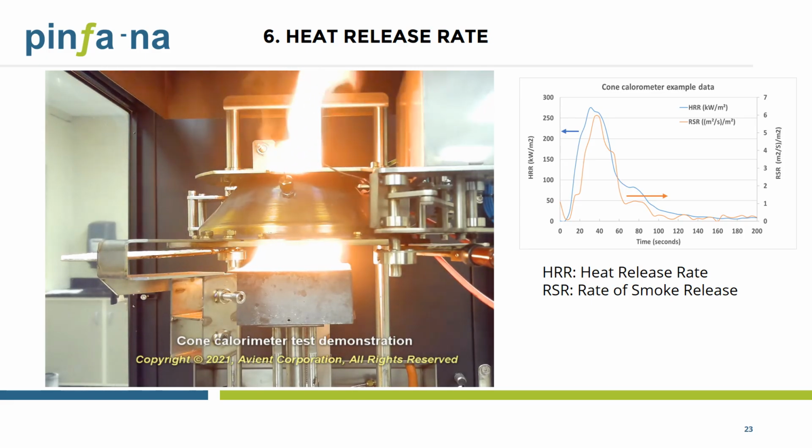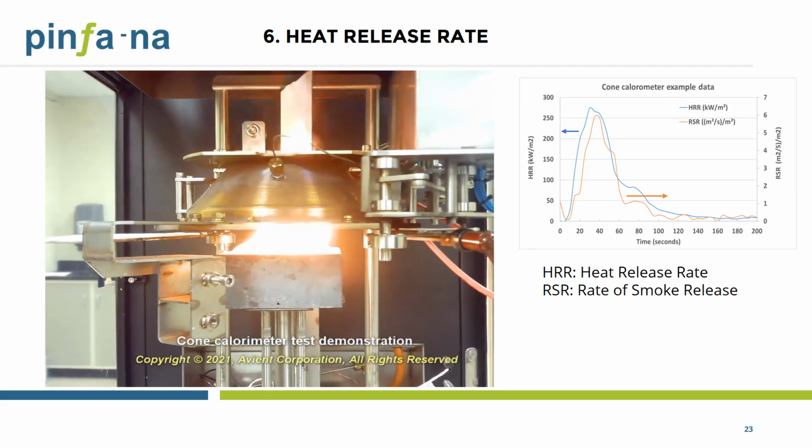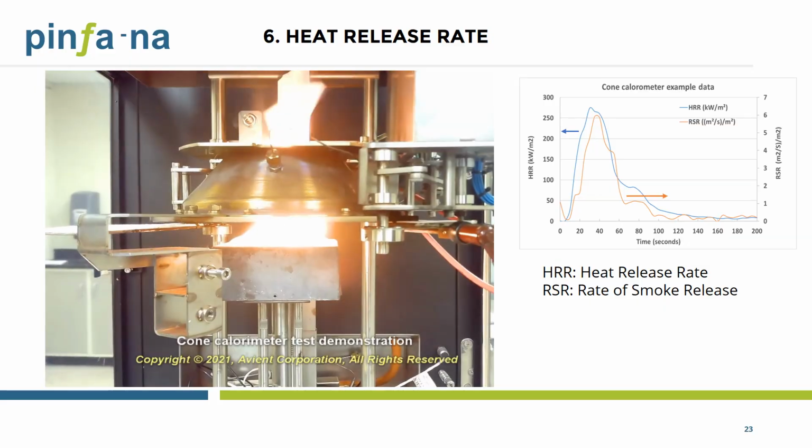Generally speaking, the time the cone calorimeter test takes depends on the sample. It can vary from a couple of minutes for thin samples to more than 20 minutes for thicker combustible samples. You have to wait for at least 120 seconds after the flame has extinguished to ensure that reignition doesn't occur before ending the test.